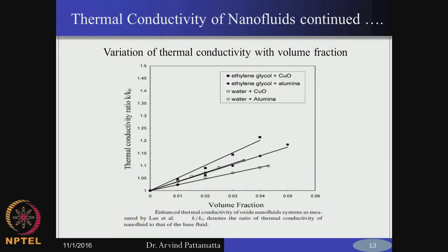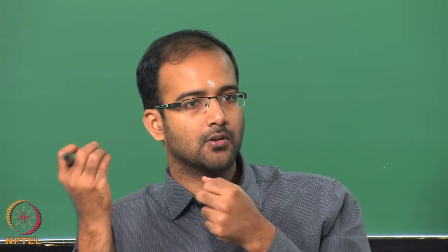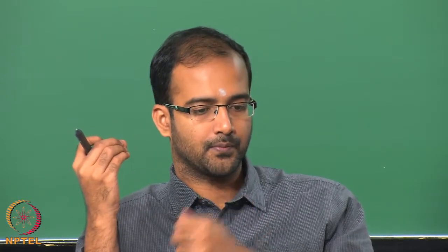Okay. So, usually we do not go beyond 5% because problems with creating a stable suspension increase, and then corrosion and pressure drop slowly will also start appearing. So, here you see the two different nanofluids. In fact, we have 4 different, depending on the base fluid also.